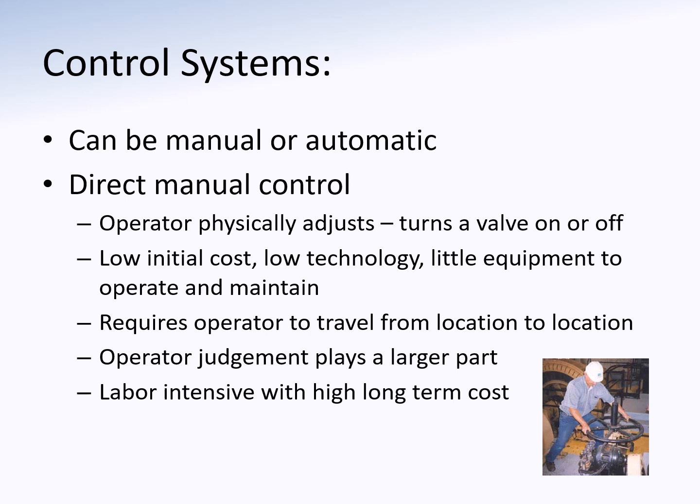I can recall for many, many years as an operator where, in order to fluctuate a reservoir that was within our system, we had to drive out 20, 30 minutes to get to a valve to close the valve, and then you'd have to go back out several hours later, open the valve. That's just how we cycled that valve until we finally got some automatic controls to be able to operate or fluctuate the reservoir level. So that's direct manual control in a nutshell.